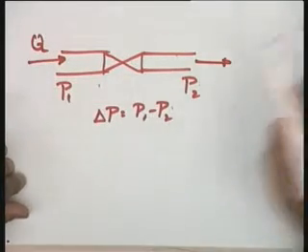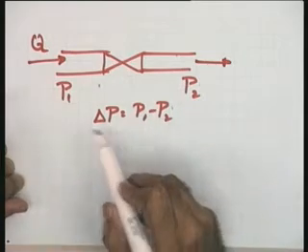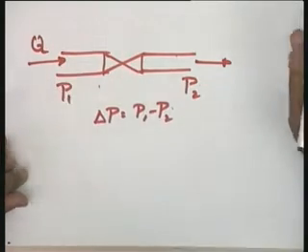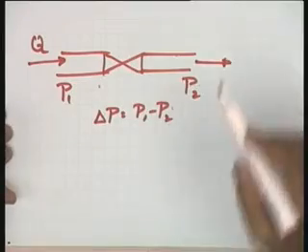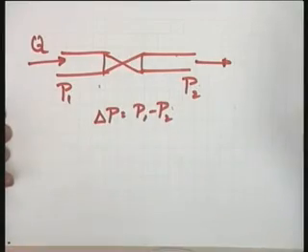Please see that the relationship between pressure difference and flow Q is highly nonlinear. It cannot be captured by a linear mathematical model. So, what normally is done in practice, this nonlinear relationship is experimentally obtained, okay? And then a suitable model is derived from that experimental data.